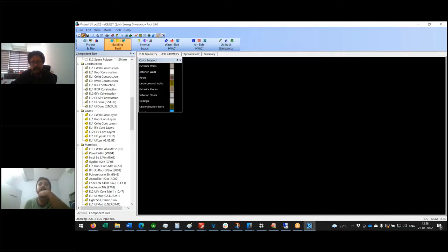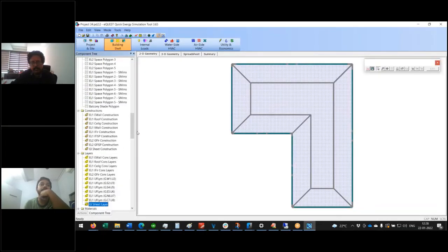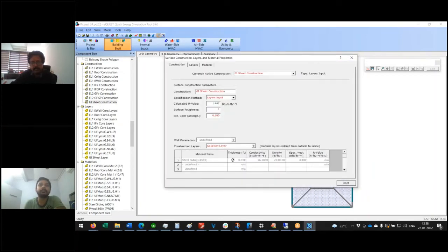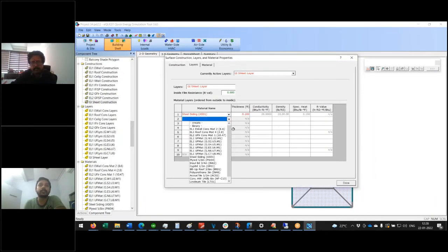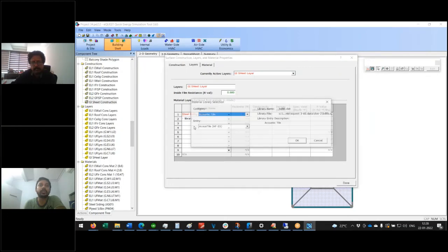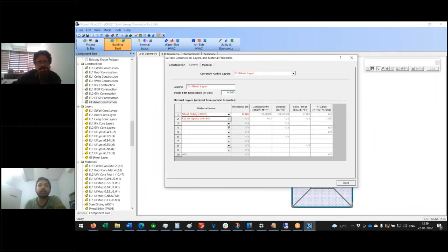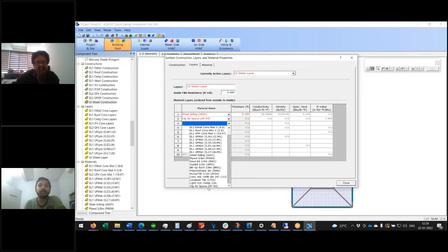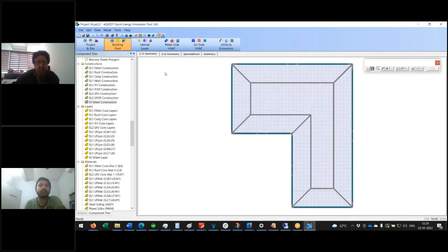So let's try put an air layer and let's see if that helps. Under layers, I'll go for library and I'll go for air film. Should be somewhere air layer. Seating airspace. Okay. Maybe one more seating airspace. Hopefully that should be good enough.